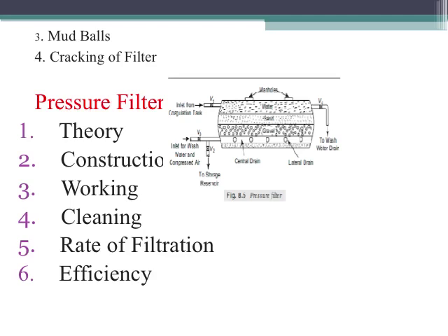Coming to the efficiency and performance, rapid gravity filters, in comparison to slow sand filters, are less efficient in removing bacteria and turbidity. They can remove only up to 80 to 90% of the bacterial load present in the water. The remaining bacteria are to be removed in the further process, that is, during disinfection.